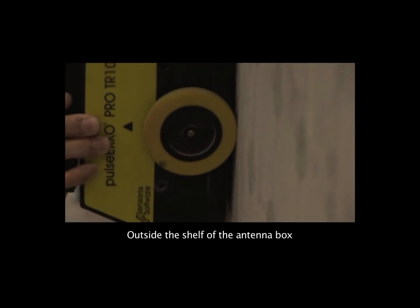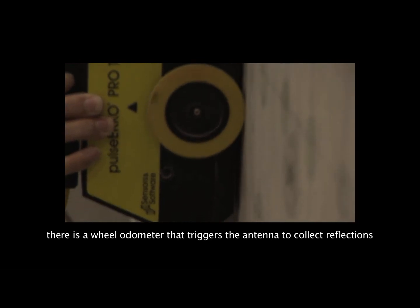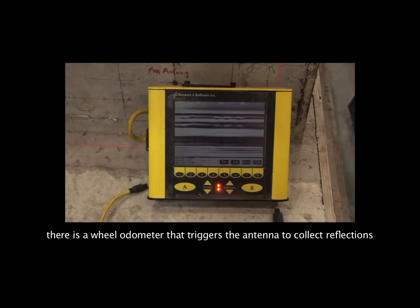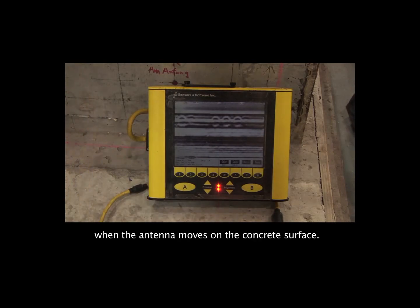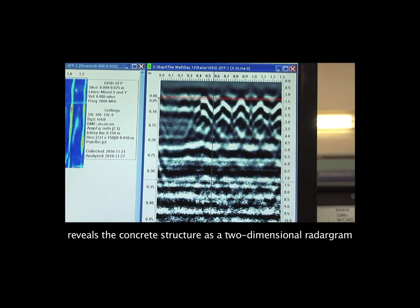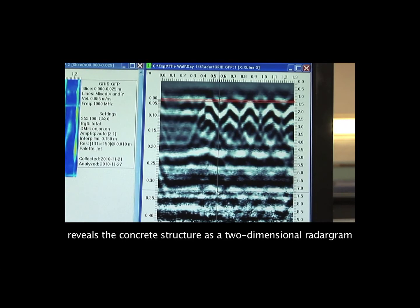Outside the shell of the antenna box, there is a wheel odometer that triggers the antenna to collect reflections when the antenna moves on the concrete surface. Compiling these waveforms reveals the concrete structure as a two-dimensional radargram.